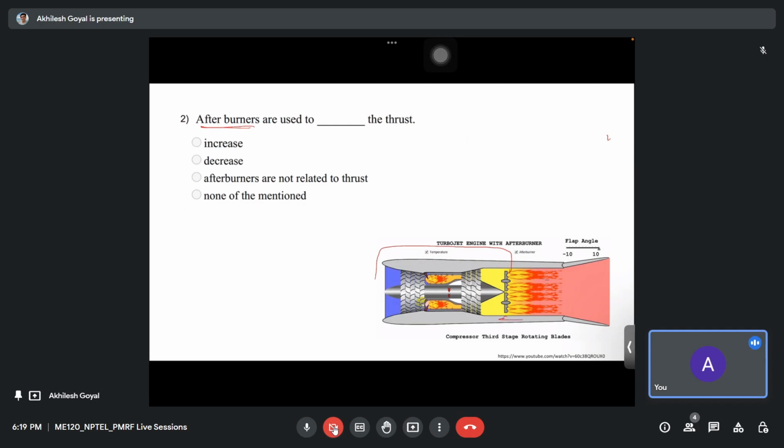So what an afterburner does is, in the case of an afterburner, some fuel is injected into the exhaust, and because of burning of this fuel, extra velocity and extra heat are generated, and that results in more thrust generation. The more push it gets if we are using the afterburners, because it injects the additional fuel into the exhaust, and that results in more heat generation and more thrust generation. Okay, so that is the principle of an afterburner. That's how an afterburner works.